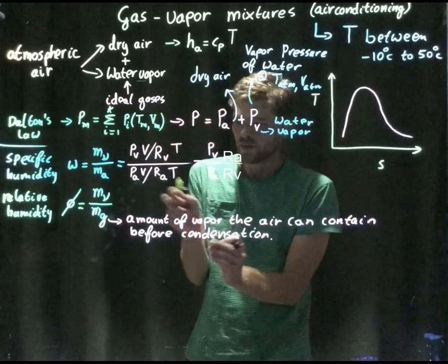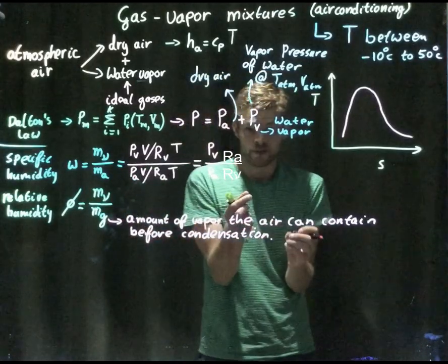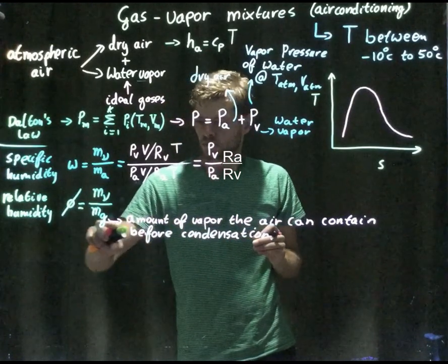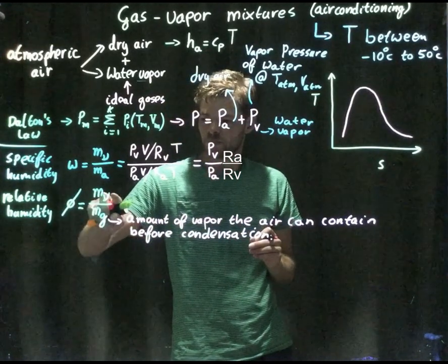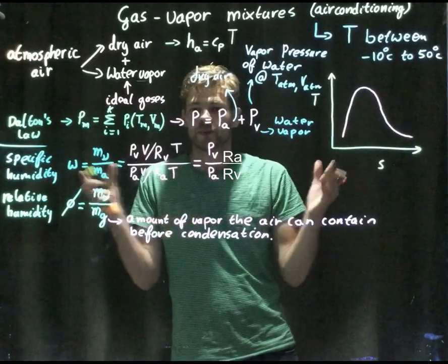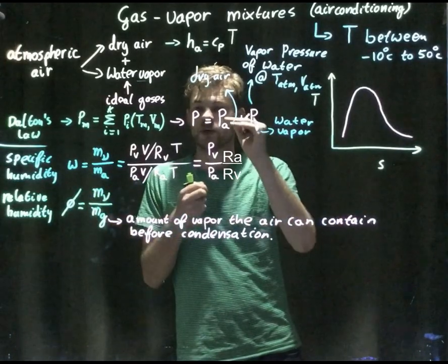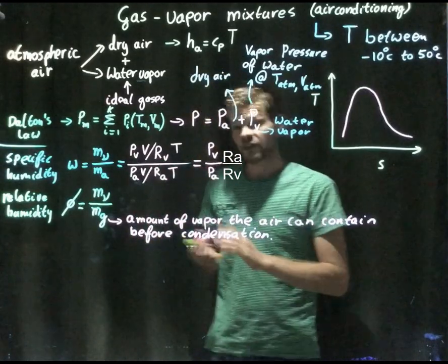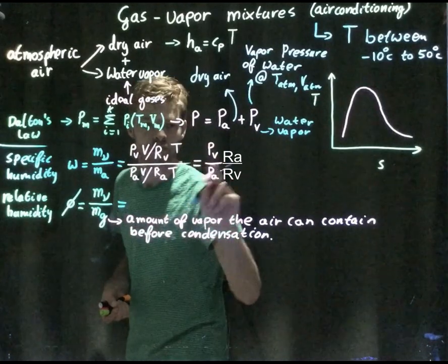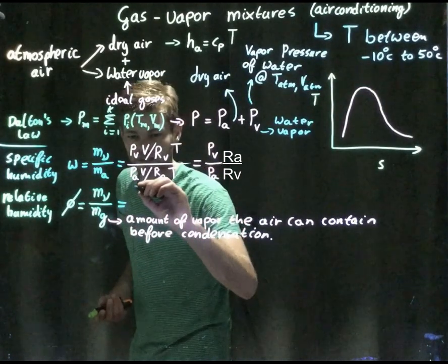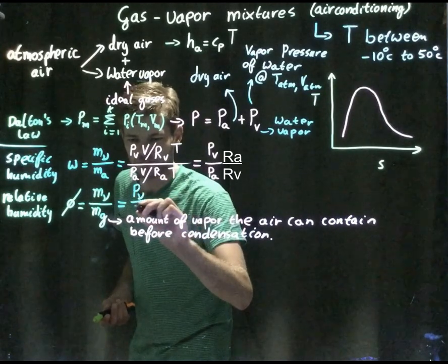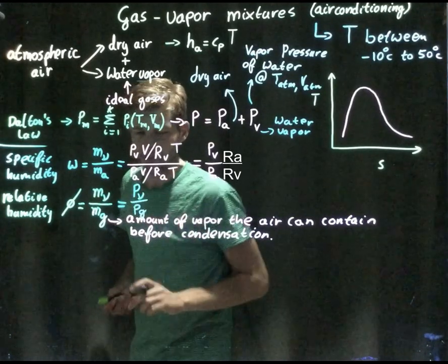So if I would add more water vapor to this mixture of air, so there will be more vapor than the mg, then that's not possible. The air can't contain this, so it will immediately condense. Well, and if I do my mathematics correctly, this will result in this relation. So it's similar to this. That says, well, it's PV, so the pressure of the vapor divided by Pg.